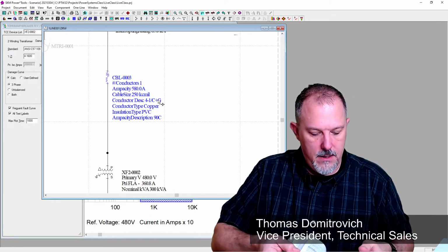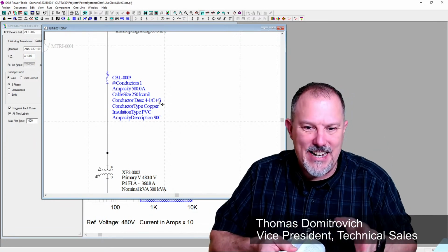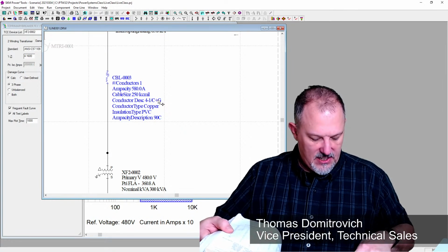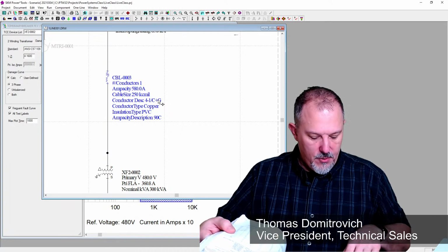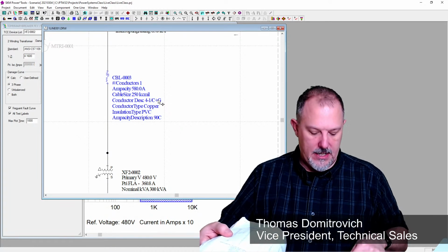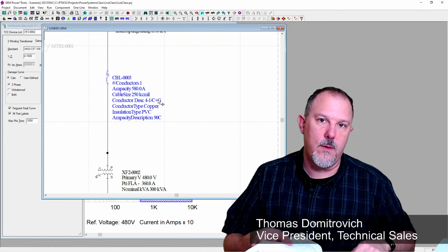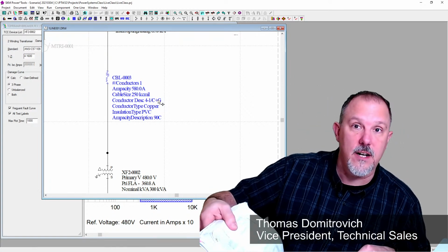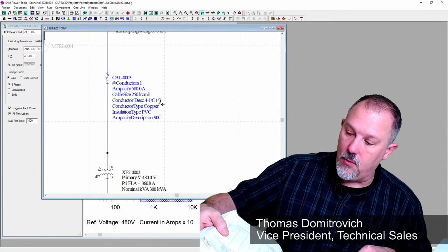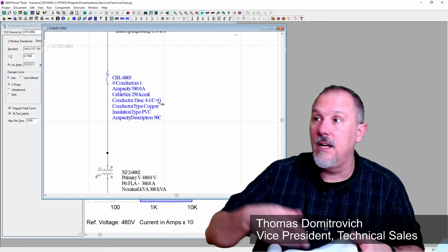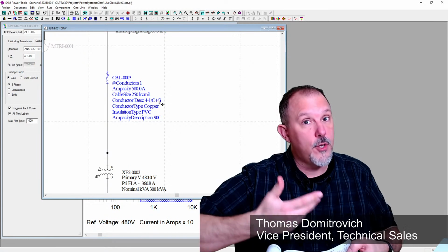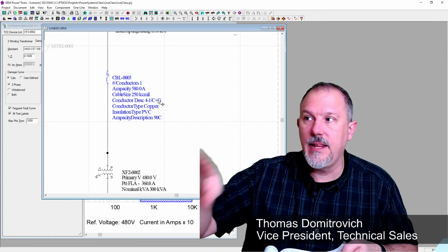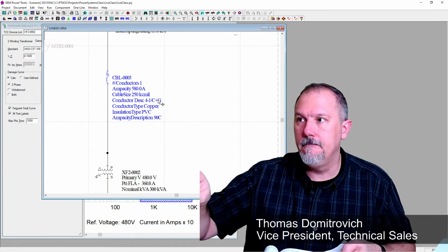What's the section, Ryan Jackson? 310.15(C)(1) tells me number of conductors in a raceway, the adjustment factors. 4 to 6 conductors is where I start. Not more than 3 current carrying conductors in a raceway for Table 310.16. I've got 2. I'm looking good. So I don't have to worry about adjusting the ampacity of this conductor.